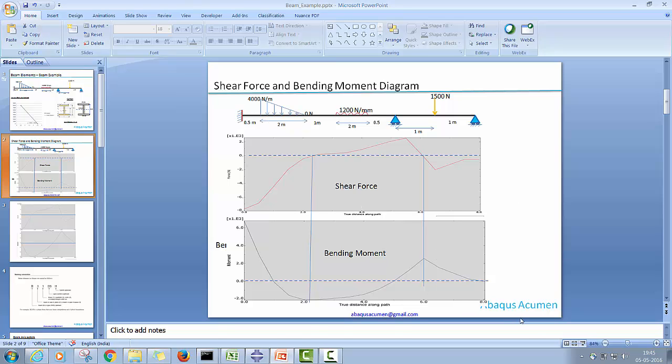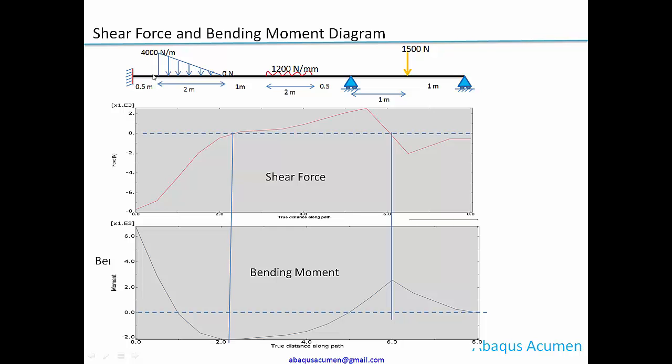So if you see this, you can see the beam with different loadings. Like here it's a fixed condition. So due to this fixed condition, we'll see some bending moment over here. It starts with some 6,500 Newton meter, and later there is a variation and due to this varying load we expect the order of 2 curve. This is what we see, and here the shear force is 0 and then corresponding bending moment is at its highest.